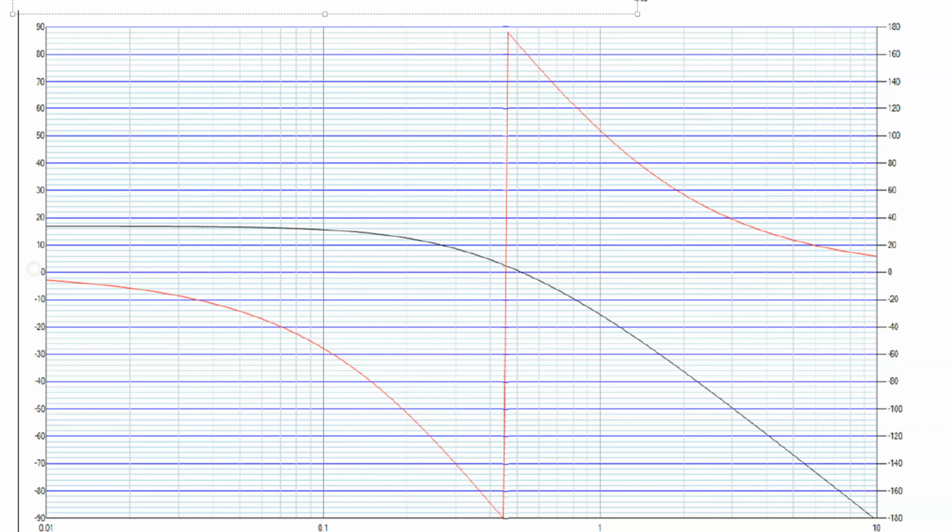The 0 dB magnitude line is the same here, but it's not a must that this is the same. The magnitude curve is black. It starts with a horizontal curve. The DC gain is in this region, and we can read plus 17 dB.